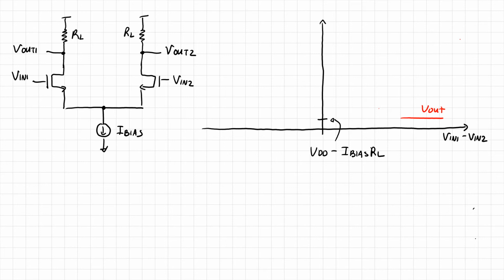Okay, so we say on the upper end here, the voltage is equal to VDD, and we say that Vout2 is up here, and I apologize, this should have been in capital letters, Vout1 down here. Now, as you can imagine, the opposite scenario happens on the other side of the curve. Vout1 is high when Vin1 minus Vin2 is negative, and likewise over here.